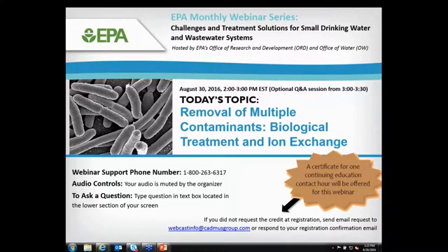We did not. In the aerobic treatment study, in the aerobic process for ammonia removal, we used a Hach test for rapid feedback of how well we were removing ammonia, and the Hach test was always backed up with samples that we collected and sent to a lab for analysis by a method that allowed more QA and QC. And then on the anaerobic side, we used dissolved oxygen. Dissolved oxygen was very effective. And then we also used Hach assays for nitrate to give us real-time feedback for how we were doing.